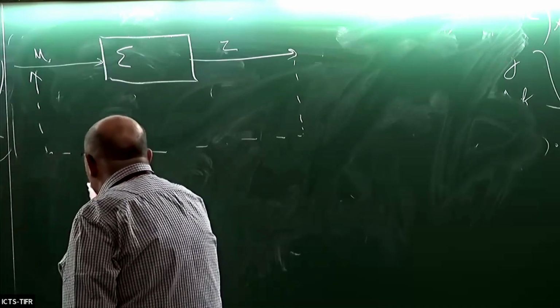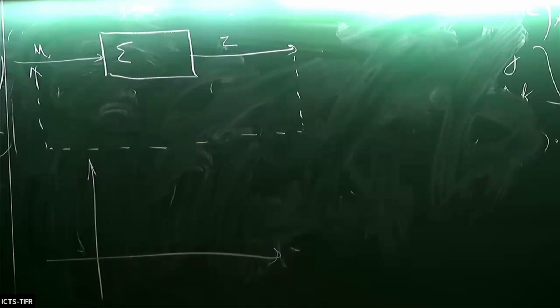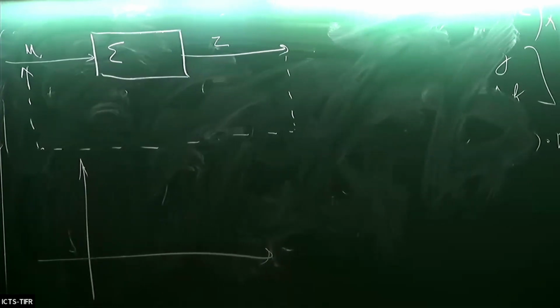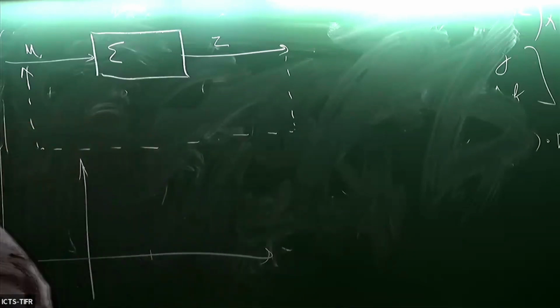And so now let me comment for a moment on this very simple formula. The maps phi t are called the input maps. What does input map mean? It means that I have initial state equal to 0, and I just measure the state produced by my input at some instant. That's the input map. So let's say here I have t. Here I have tau, let's say.